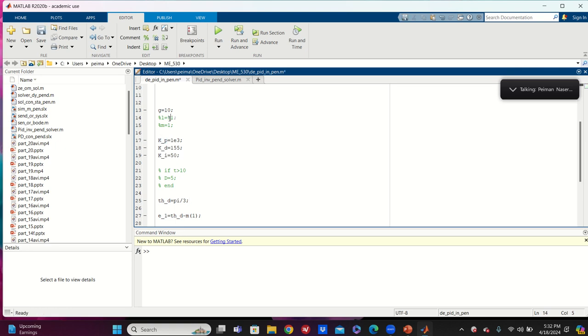Here it was 60 degrees. That's right, I said 60-degree desirable angle, right? But it is a trade-off, guys, between the control command U or torque in Newton meter and the time of the operation. So I tuned more by increasing Kp, Kd, and Ki.